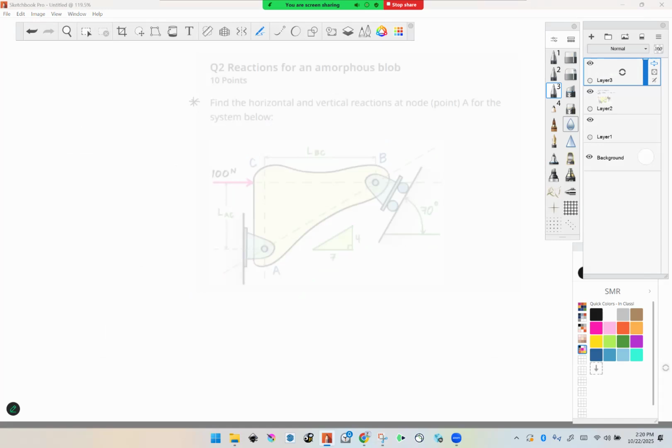I'm going to start with the free body diagram. And so, the shape of this body really doesn't matter, kind of if you draw it as a triangle or whatever. The important thing is that we put a hole there for where we're taking the bolt out. We put a hole here for where we're taking the bolt out. Now, when I teach this early in the semester, I kind of emphasize what we're doing. So I draw these as holes. But as we become more sophisticated, these are going to migrate just to dots like that. So I'll leave it like that for this particular solution.